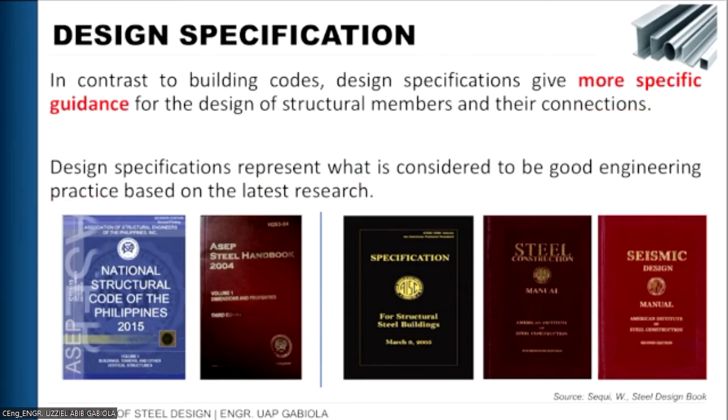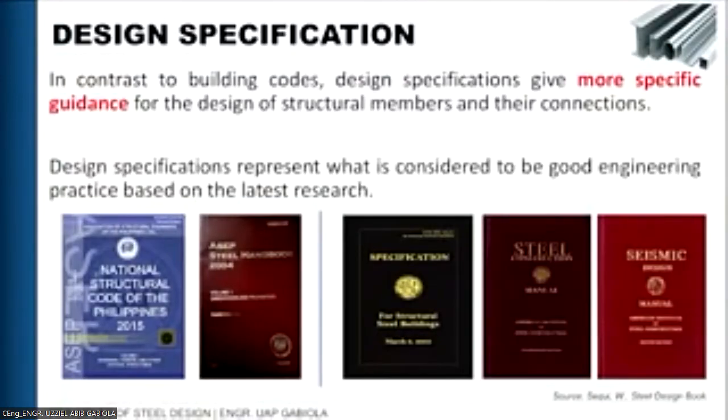Why? Because these specifications are being updated rigorously, especially when a calamity happens. These specifications are always updating. Let's say, for example, a strong earthquake happens in an area, and new faults appear. If there are new faults present, the maps available in this specification should be updated so that if ever we are trying to design future structures that may be located on these fault lines, we are able to consider the loadings that need to be applied as part of our analysis.